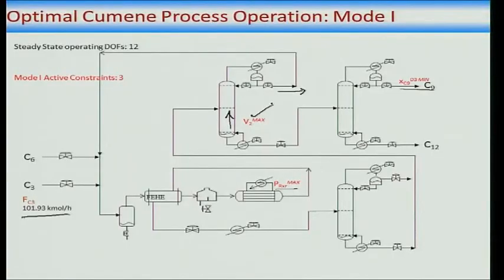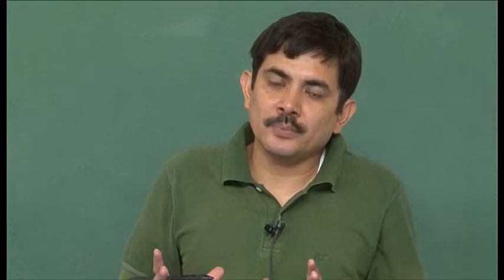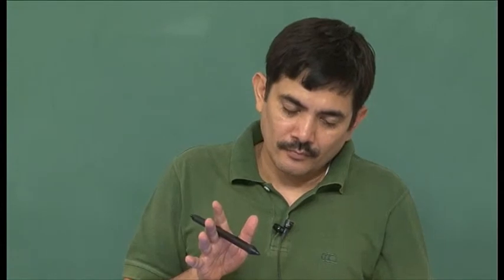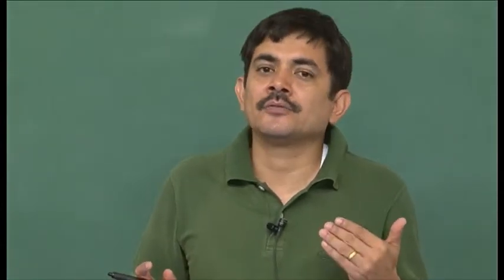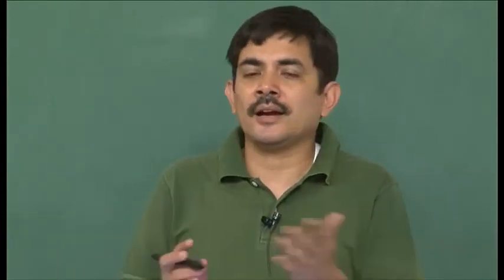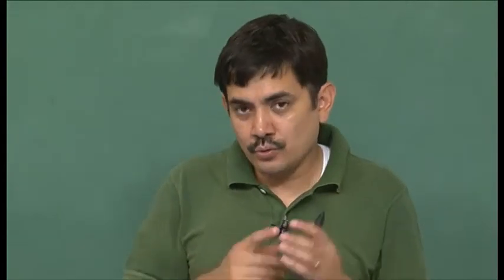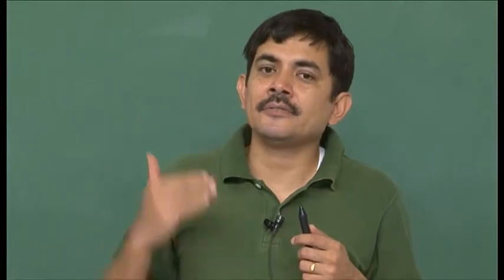So this makes sense. P reactor max is maximum because as you increase the reactor pressure, the rate of reaction of the main reaction and the rate of reaction of the side reaction go up by the same amount. The ratio of the main reaction rate to the side reaction rate remains the same regardless of pressure. So what you have is you get an increase in conversion, but you do not have any selectivity penalty.